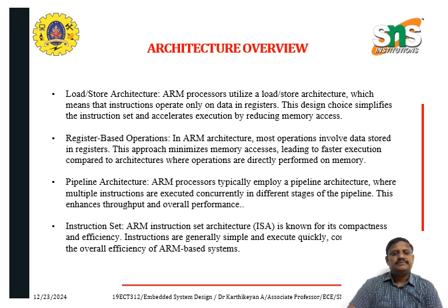Architecture overview. This is a load and store architecture, which means instructions operate only on data in registers. This design choice simplifies the instructions by reducing memory accesses. Register-based operation in ARM architecture mostly involves data stored in registers, minimizing memory access and leading to fast execution, unlike computer architectures where operations are performed directly on memory.